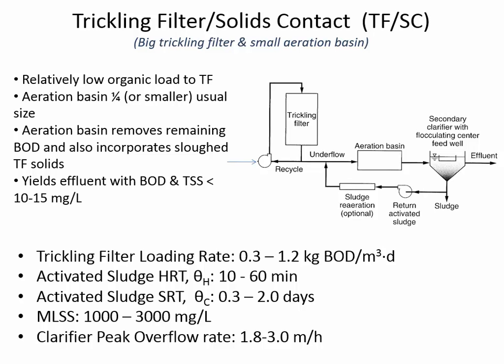And so the activated sludge is the afterthought and the trickling filter is the main event in a TF/SC, trickling filter solids contact. What you'll notice is that the hydraulic retention time in activated sludge is very, very short, 10 to 60 minutes.